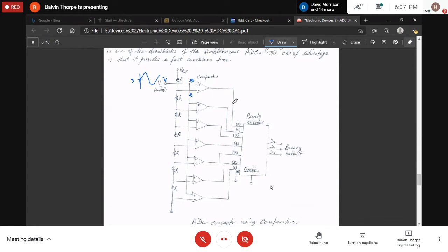So be that as it may, that comes here and it says, okay, when the enable samples, it realizes that on this line there is not really a voltage, because the reference voltage is greater than the input voltage. So it's going to say, okay, there's nothing here, which makes sense because it is looking for, let's say, 7 volts, and I'm just using this rule. It's looking for 7 or greater. Sorry, it's looking for a 6 voltage rather, or greater, right? And if it sees that it is less, it's going to be, as far as I'm concerned, 0. Nothing's going to be coming in.